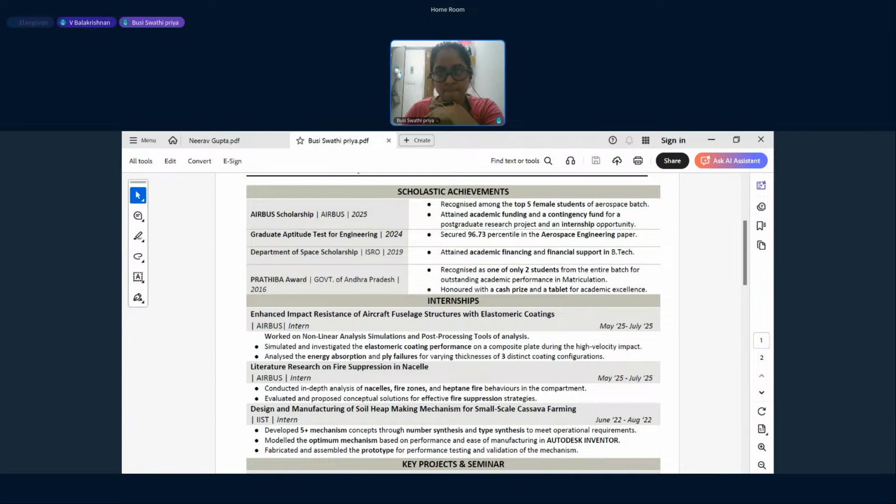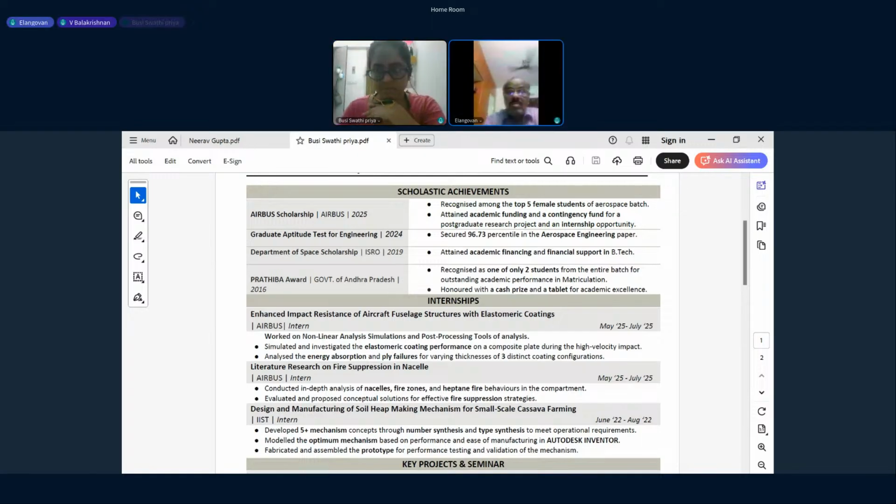So you showed the temperature distribution. It is okay, but what is the temperature at the turbine entry? What is the turbine entry temperature? Around 1200 Kelvin. 1200 degree Kelvin or 1200 degree centigrade? Sorry, sir. 1200 degrees centigrade.